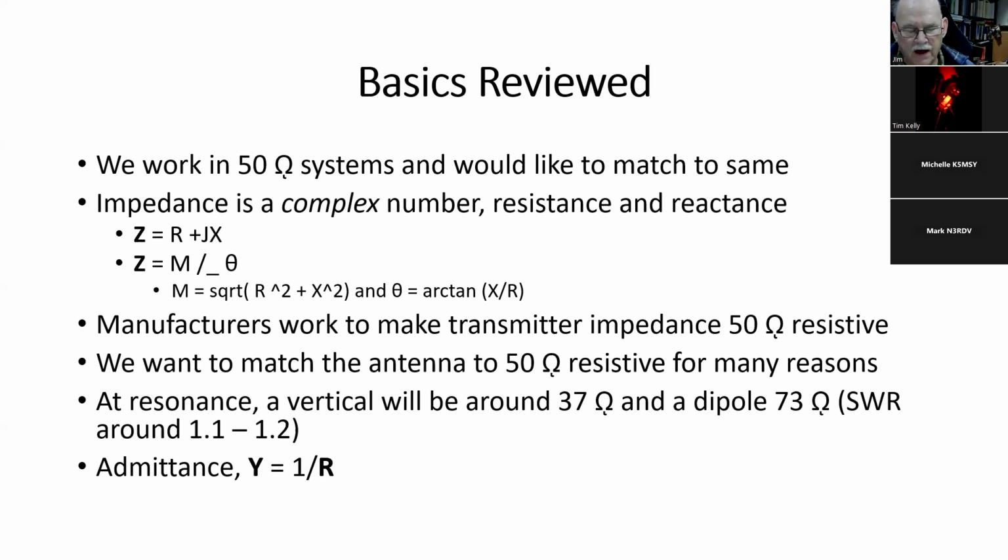So bottom line here is when we are putting impedances in series, we just add them. When we are putting impedances or reactive inductors in parallel, life is easier if we deal in admittance. And I'll show you how to do that graphically without the ugly arithmetic. Any questions so far?